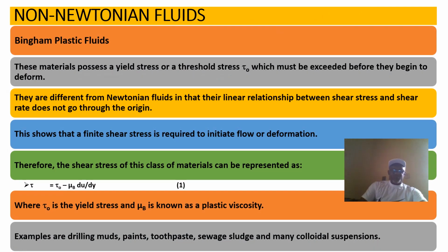Now, non-Newtonian fluids. You have Bingham plastic fluids. These materials possess a yield stress as a threshold stress, which must be exceeded to begin to deform. They are different from Newtonian fluids in that their linear relationship between shear stress and shear rate does not go through the origin. Remember I said for Newtonian fluids, it goes through the origin. This shows that a finite shear stress is required to initiate flow or deformation.